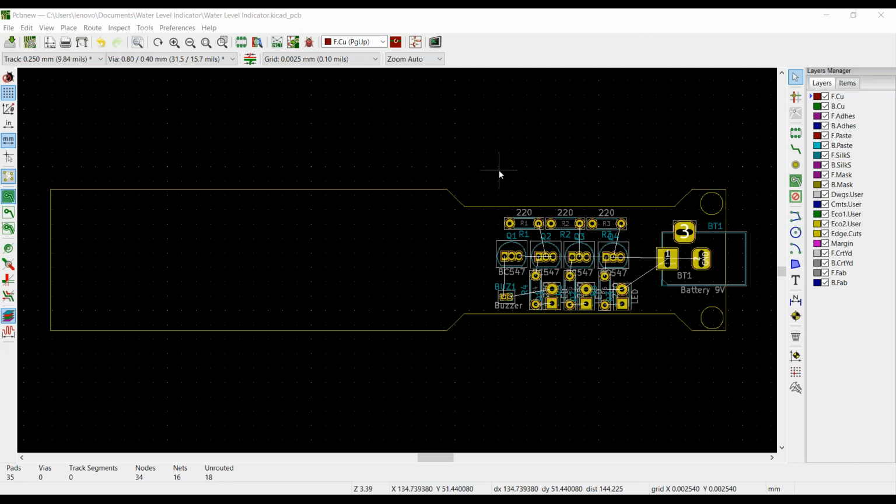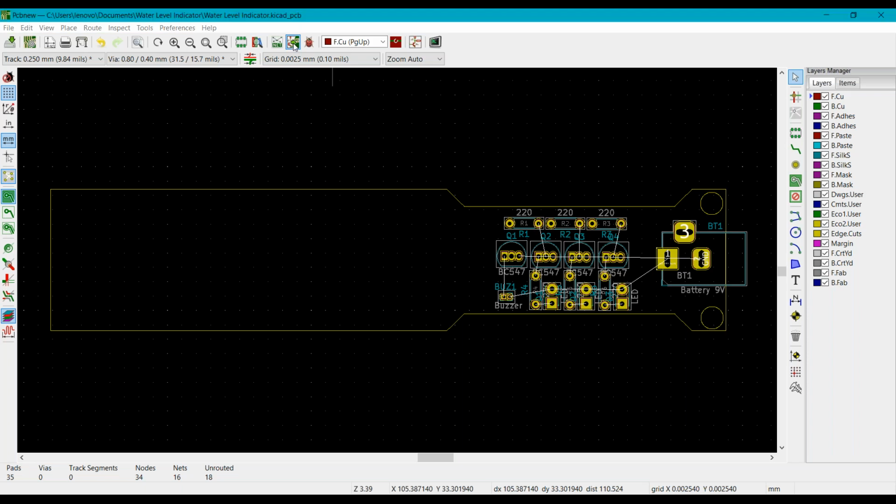So yeah, we had designed the board layout yesterday, and this is our design. Now, how these components are coming in this area. You must all be aware that there is an icon named Update PCB from Schematic. This is the only icon which will load your generated schematic, the netlist which you generated while making the schematic. So just click on this.